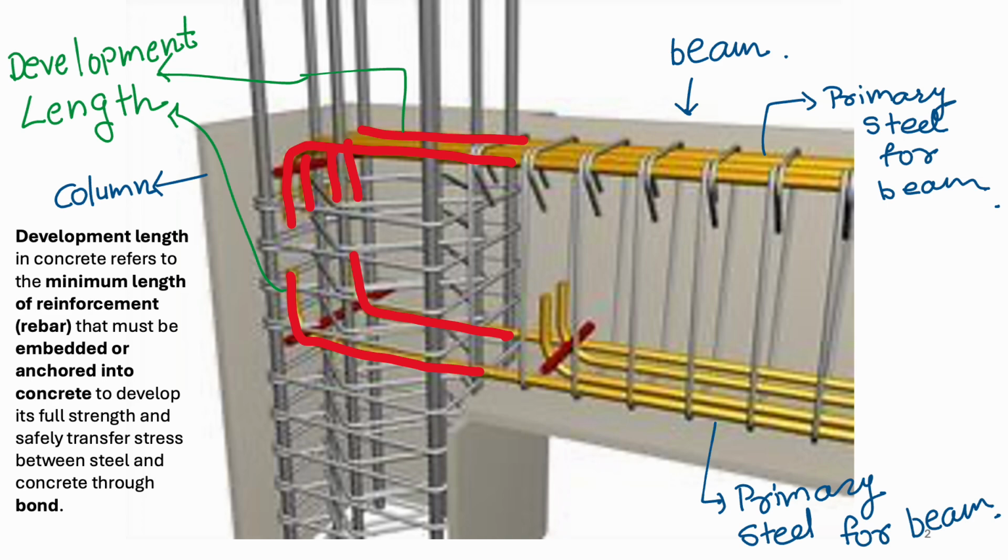Hi guys, today we will cover development length in concrete. The first question, what is development length? Development length in concrete refers to the minimum length of reinforcement rebar that must be embedded or anchored into concrete to develop its full strength and safely transfer stress between steel and concrete through bond.